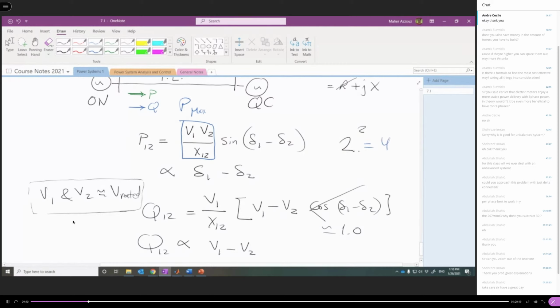And this will help us reduce the need for land to install transmission lines, and decrease the power density of the transmission line. But of course, as you double the voltage, you have to double the height of the tower, because as I told you before, we use the air to act as an insulator between the line and ground.